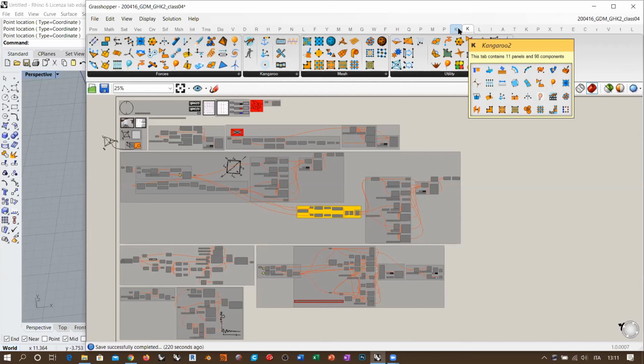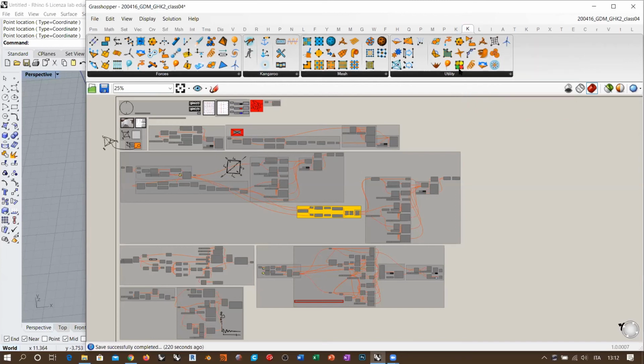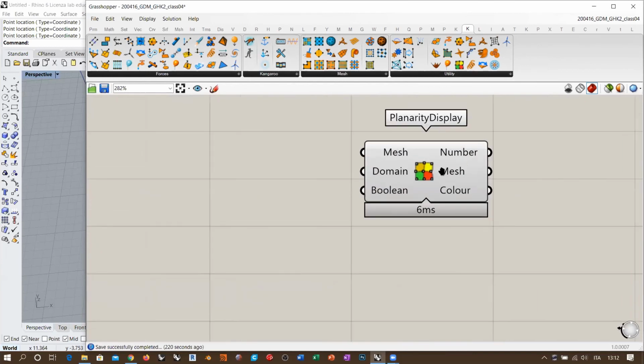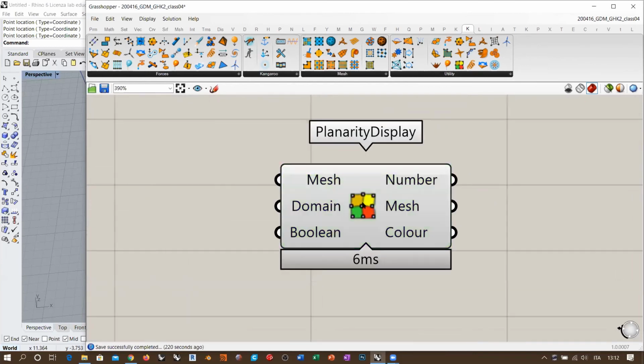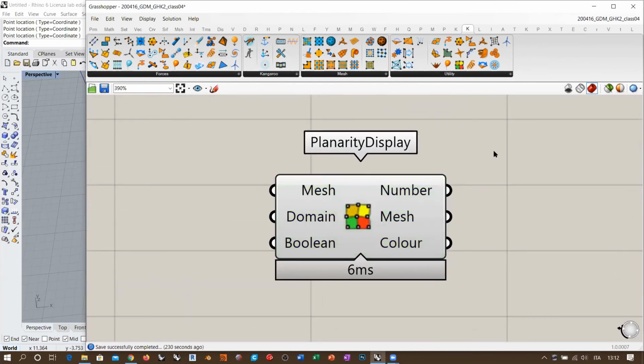And the last thing, speaking of which, this component here makes it possible to analyze the deformation that you get inside your mesh during the simulation and understand if you can eventually bring your deformed geometry to a production process where you use cheap and fast technology, like, for example, cutting technology.